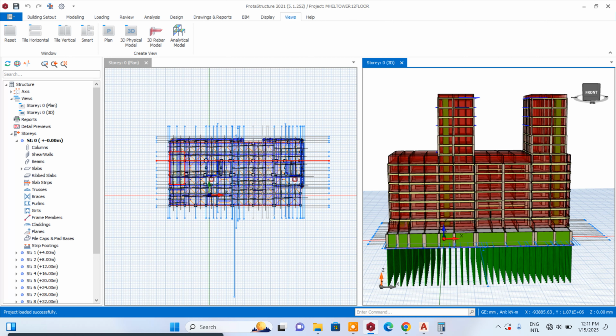I know that somebody has already learned something: you can always explore different ways of carrying out your design. If your pile cannot work, you go for a raft. If it's raft on beam or beam on slab, depending on the type of raft you choose, and it doesn't work, you can go for raft on piles.